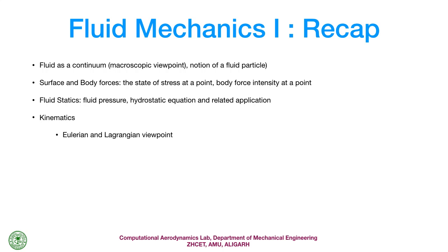In the Lagrangian viewpoint, you consider one fluid particle as your system, and the variation of this fluid particle, or the interaction of this fluid particle with the force, is the object of study, and how this changes is basically the point. Now, in the Eulerian viewpoint, you do not consider a single particle, but a whole bunch of particles at a point, and you do not sit on the fluid particle; you experience this on a bunch of fluid particles. That is the Eulerian viewpoint.